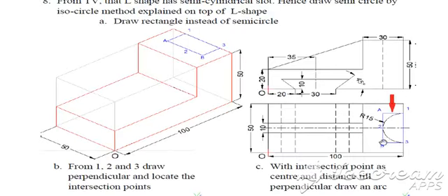Now let's see how to draw this semicircle. We can observe here that the semicircle has a radius of 15 mm. So this A1 is 15 mm, AB is 30 mm and B3 is 15 mm. So simply draw this rectangle at the given position. This is at the top, so here it should be drawn over here. So this should be 15 mm, this should be 30 mm and this B3 should be 15 mm. Also mark the midpoint as 2.